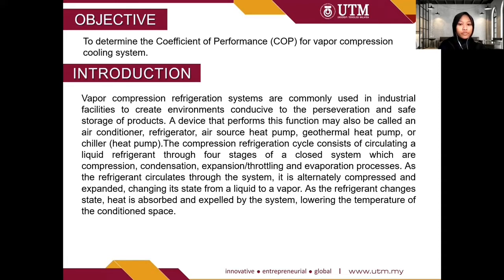The compression refrigeration cycle consists of circulating a liquid refrigerant through 4 stages of a closed system, which are compression, condensation, expansion or throttling, and evaporation processes. As the refrigerant circulates through the system, it is alternately compressed and expanded, changing its state from a liquid to a vapor. As the refrigerant changes state, heat is absorbed and expelled by the system, lowering the temperature of the